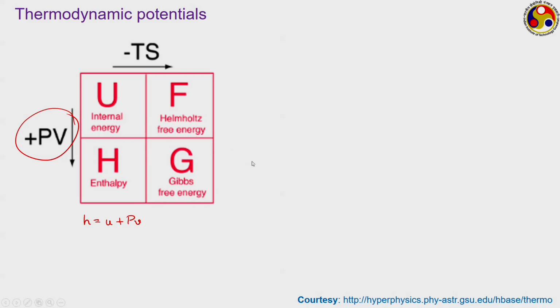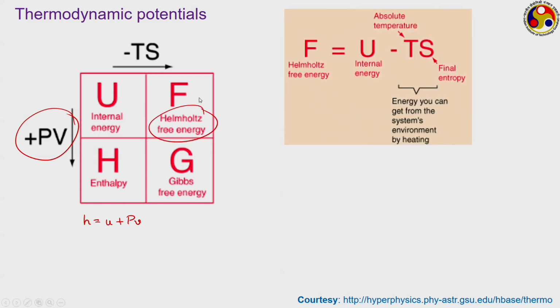That is called the Helmholtz free energy. As shown here, it is the Helmholtz free energy, and it is represented as U minus Ts. Just follow these symbols. Once we subtract Ts from this internal energy, we get this Helmholtz free energy. Or in intensive sense, we write small f is equal to small u minus T into small s. In certain textbooks a symbol small a is also used, like the book that we are mostly following in this course, the book of Cengel and Boles, that actually uses small a as a symbol.